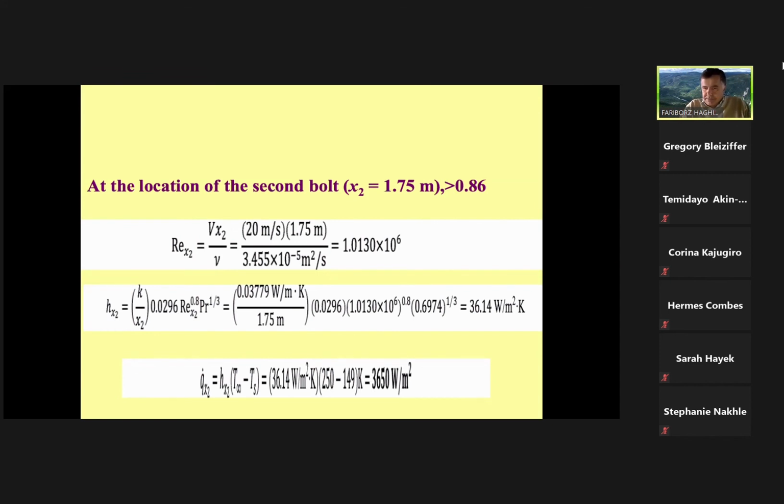That's correct, sir. But do we separate them? Because there is a Nusselt number for laminar and for turbulent. Right? And for the turbulent, yes, it includes laminar also. But if you're trying to calculate the average heat transfer, you can use the last equation that is given to you, because that last equation considers the contribution of the turbulent and laminar.